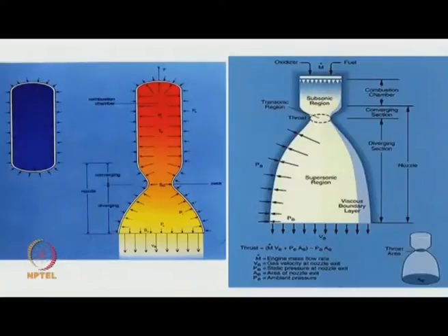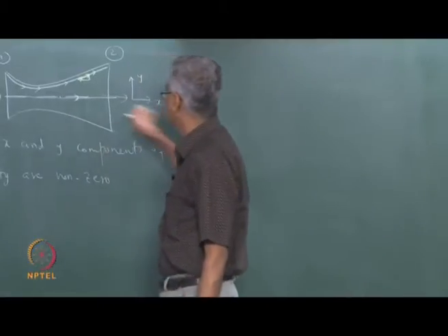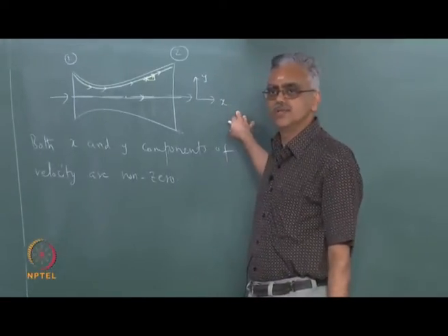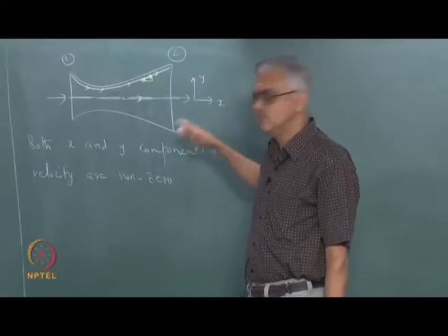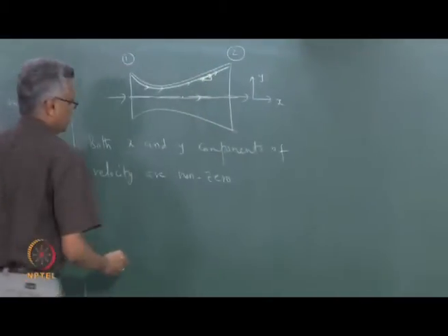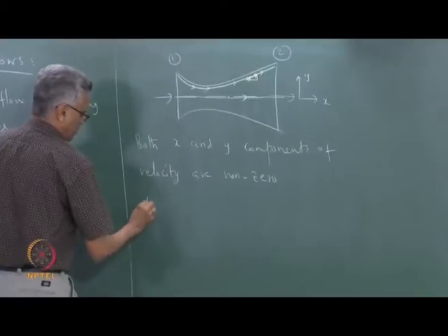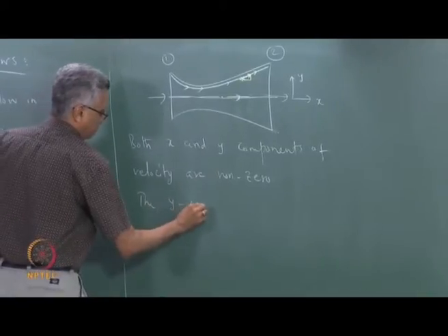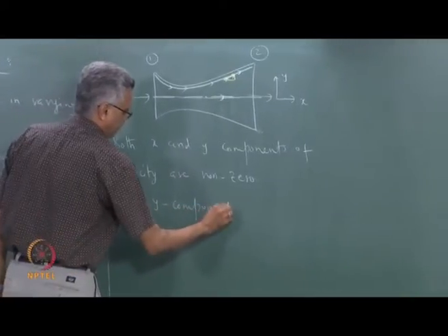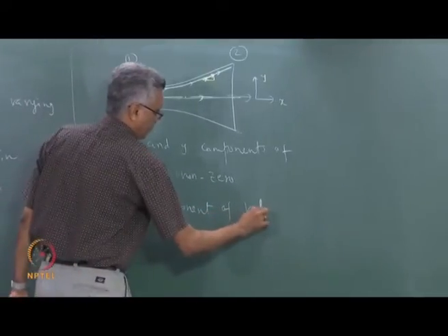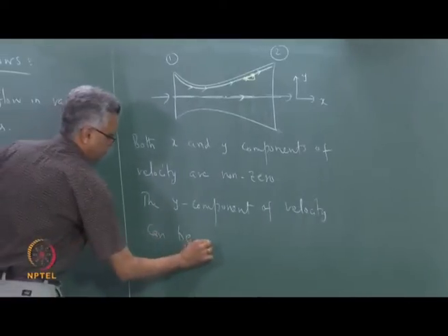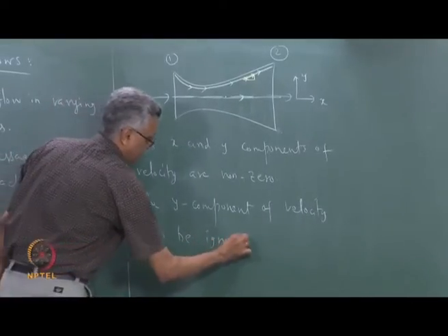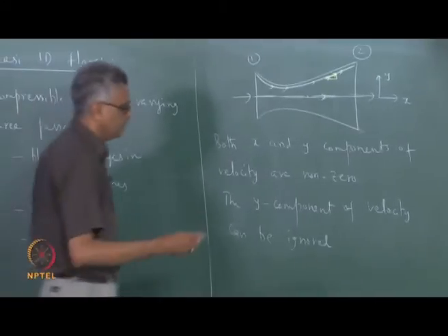Which tells you that the effect of area change is to accelerate the flow in the x direction much more than the acceleration in the y direction. So, in most of these applications we can actually ignore the y component of velocity when compared to the x component.